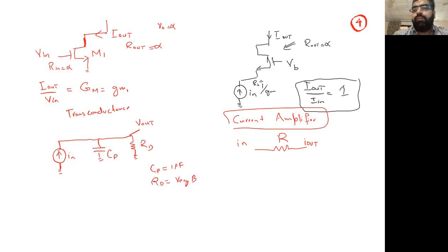So what's going to happen because of the very big value? Our cutoff frequency is going to be very low, and ultimately it will start impacting at a lower frequency. So the bandwidth will be very small in this circuit. And we don't want this configuration.